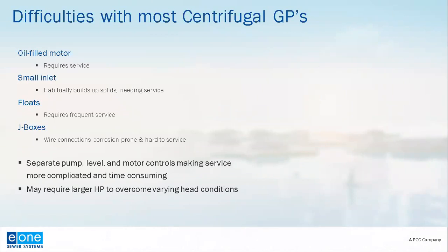Again, our pumps are serviceable. If there's an issue with the motor on any one pump, it can be fixed on site, and the asset can be returned to service. If you have a bad motor on a centrifugal pump, typically you're not going to drain the oil out of it on the back of the truck and replace it. You're going to push it and pull it conceivably without doing any troubleshooting diagnostics. And who knows if you're ever going to get to the root cause of the problem.